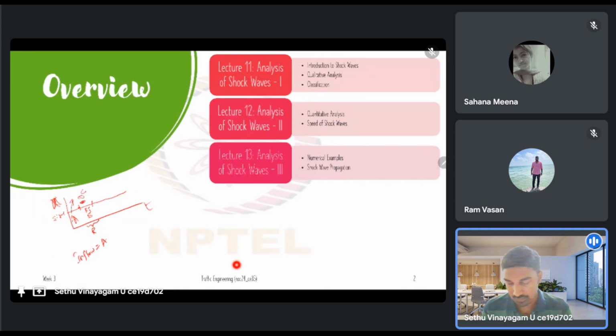So we have three different traffic states, and shock waves are created when two different traffic states meet, right? You have traffic state A and traffic state B. If you look at the fundamental diagram, what is traffic state A? Let us assume it is somewhere in the free flow condition. B is the jam condition, and C is at the origin, zero flow, zero density. So what is the traffic state between A and B? It is a backward forming shock wave. That is the shock wave that will be created between A and B.